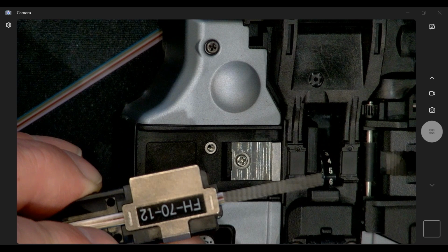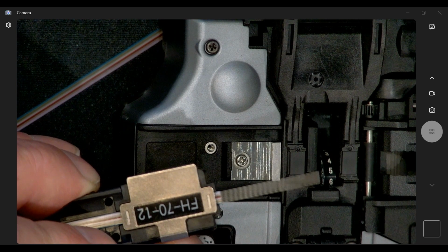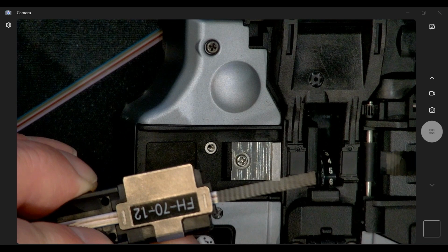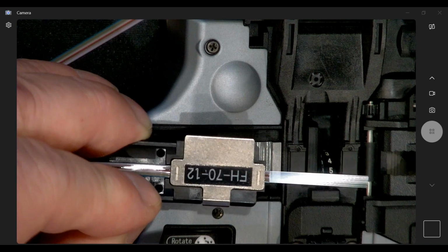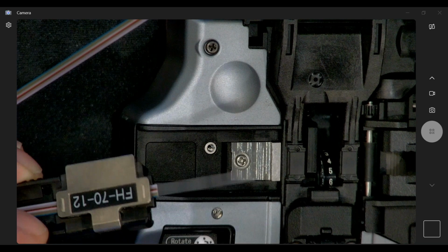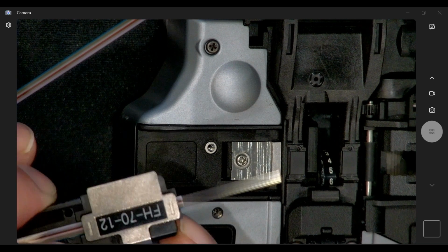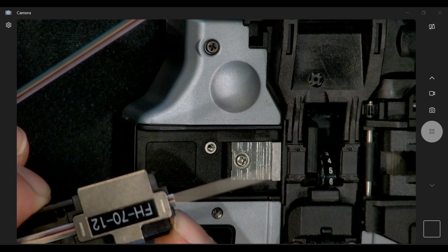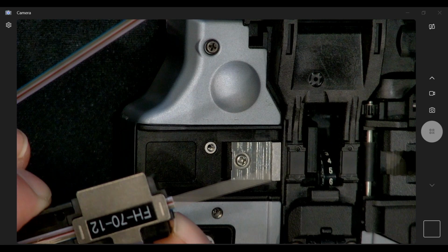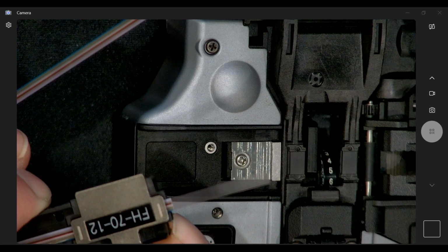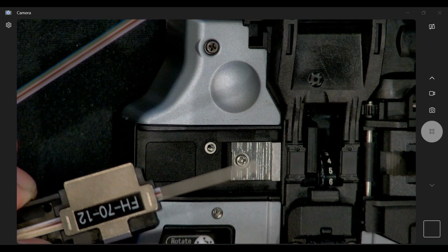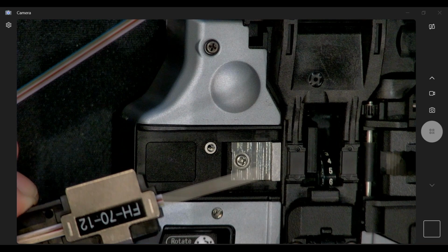When customers are doing their own repetitive work, and I'm overviewing everything as an instructor, at the point of them going to load this fiber into the cleaver, I ask them to hand me that fiber holder. If you do not see this, I would really be cautious about pushing it through your cleaver. If you've got an entanglement, if you've got a separation, here's where the actions of the technician become a problem for the cleaver.